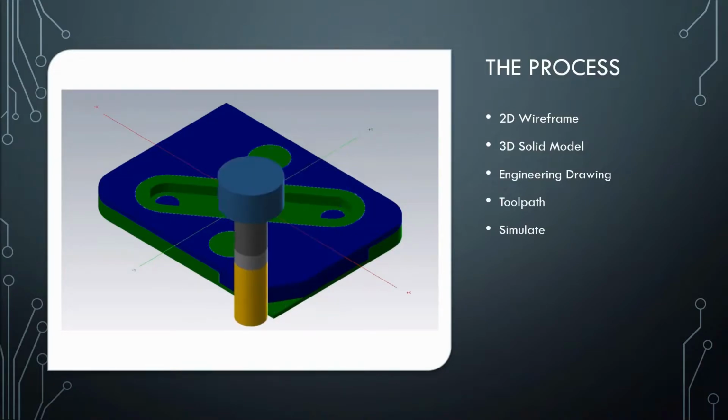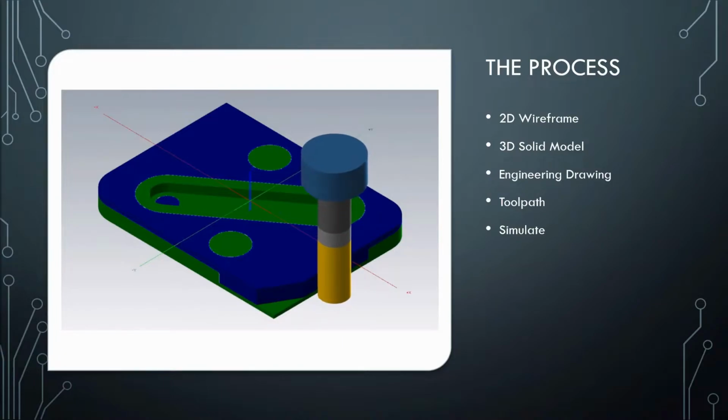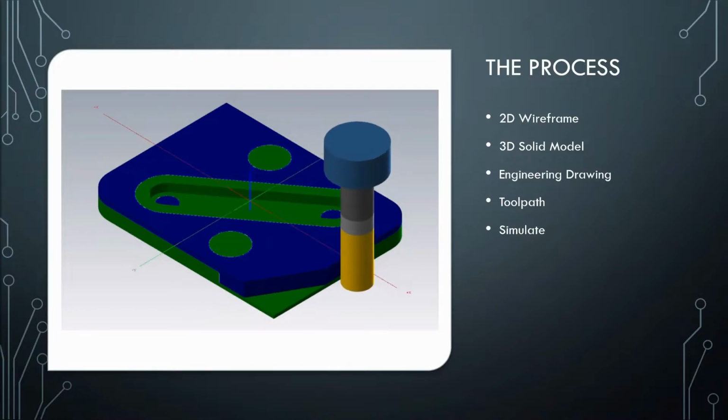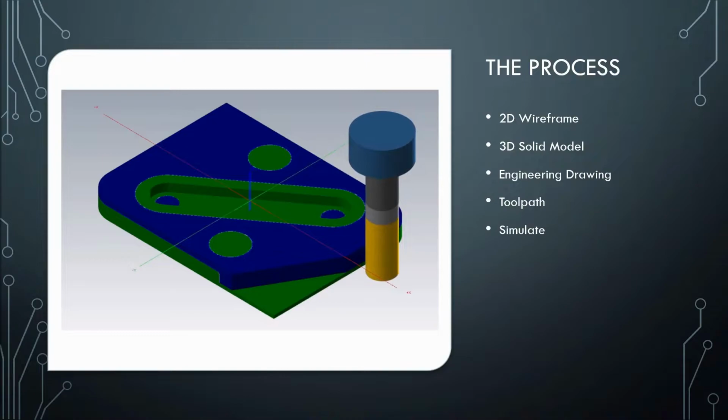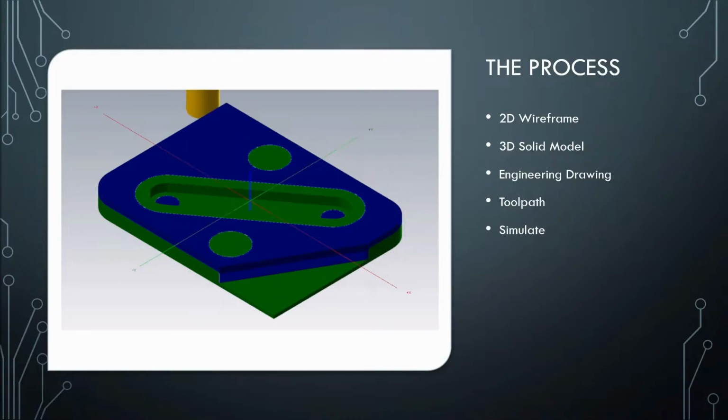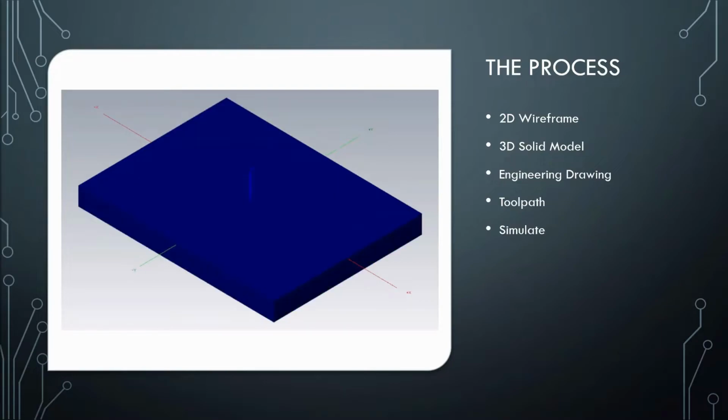One particularly useful feature of Mastercam Simulator is the compare function. Provided that you've created a 3D solid model of your part, Mastercam is able to compare the simulated toolpaths to the original 3D model and bring to your attention any details that do not match up perfectly. This is a very useful troubleshooting step and will save you a lot of headaches. Once all the back and forth with the simulator is finished, it's time to post the program.